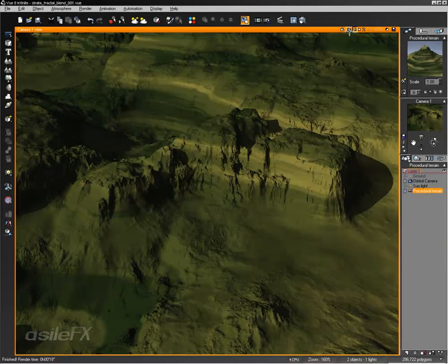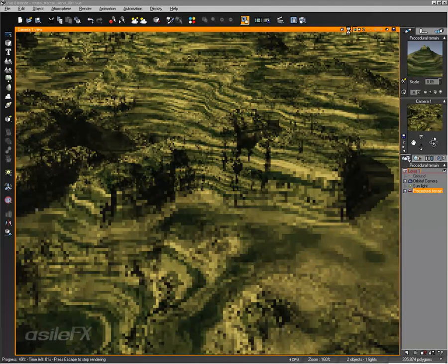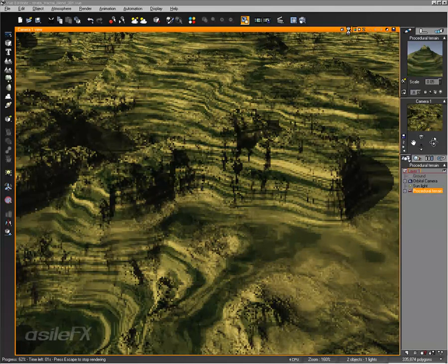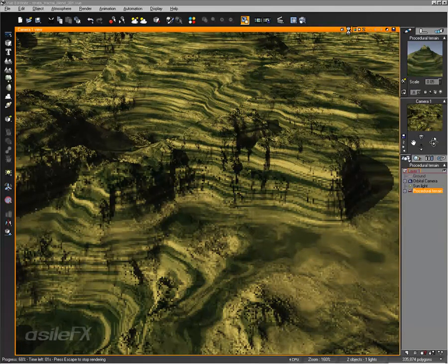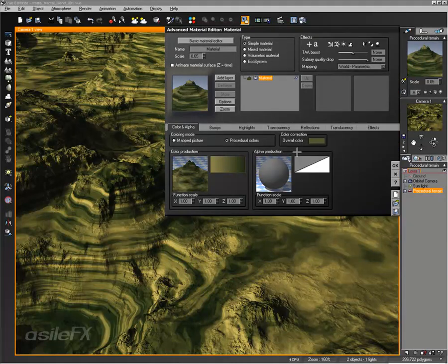And because the fractal is so large now in this mapping mode, it does stretch out a little further, looks a little better. If we were to get something a little closer to how it was looking before, we could type in a value of 0.05 for the material. But we're still going to see a much better layering effect when using the parametric mode. And it wouldn't really matter if you're using the world or object parametric mode. It should give it just about the same result either way. It's just whether or not you're moving through the surface.